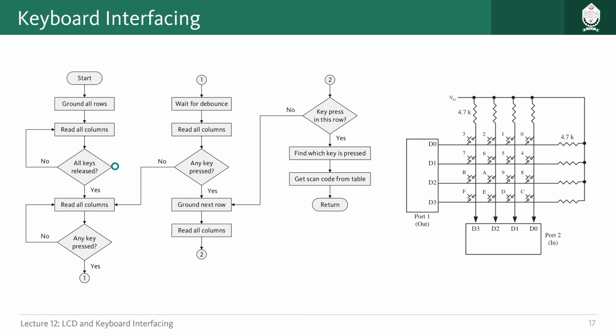But for the microcontroller to figure out that key press and execute whatever is needed may take a very little time, maybe 50 or 100 milliseconds. After it completes that, it cannot just do the same thing again, because the key is still pressed, so it goes back to its initial condition to look for another new key press.